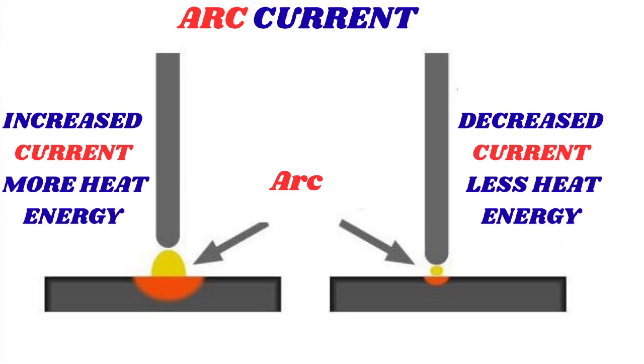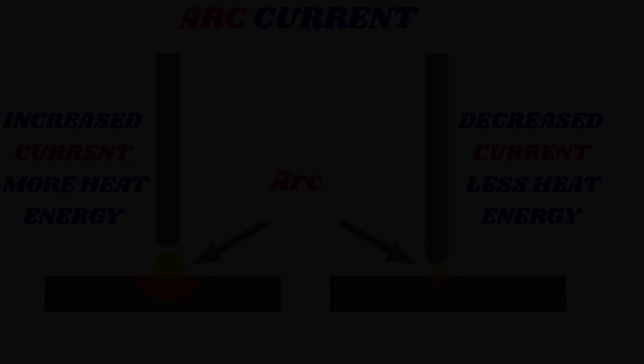2. Arc current. The arc current also affects the effectiveness of arc extinction. Higher arc currents can make it more difficult to extinguish the arc. When the arc current is high, the energy dissipated by the arc is also high, making it more challenging to extinguish. The arc current is influenced by several factors, including the load current, the fault current, and the circuit breaker's interrupting capacity. 3. Arc length.